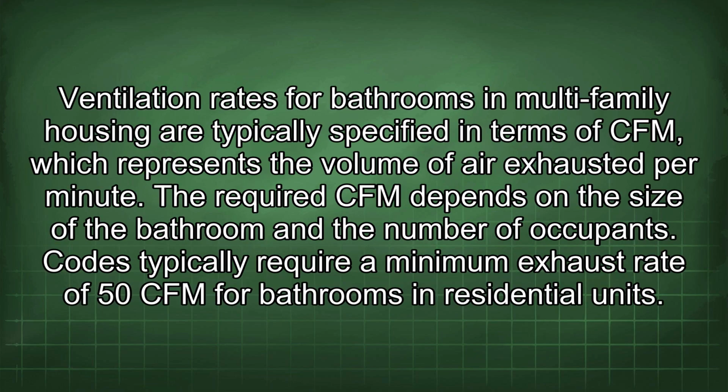Ventilation rates for bathrooms in multi-family housing are typically specified in terms of CFM, which represents the volume of air exhausted per minute. The required CFM depends on the size of the bathroom and the number of occupants. Codes typically require a minimum exhaust rate of 50 CFM for bathrooms in residential units.